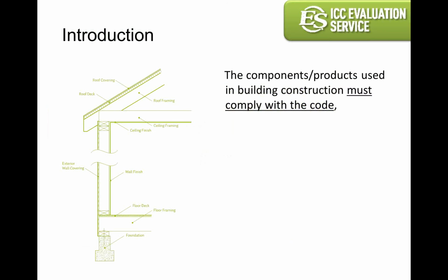Really, when we get into, for example, the building code or the residential code, there are various restrictive requirements and design requirements that we have to look at as far as the design and construction of the building. And each one of those components has certain code requirements, whether it be maximum spacing of studs, or minimum thickness of wood structural panels, or certain insulation requirements, or surface burning requirements, different things like that.